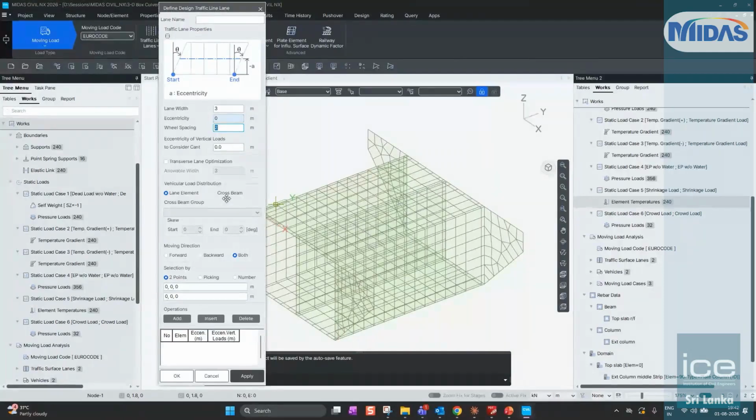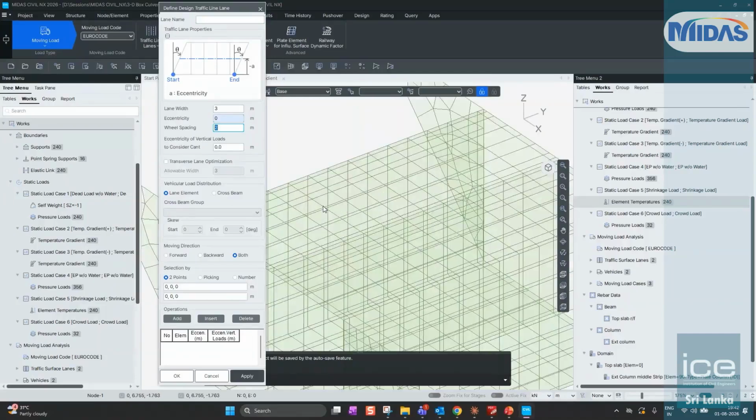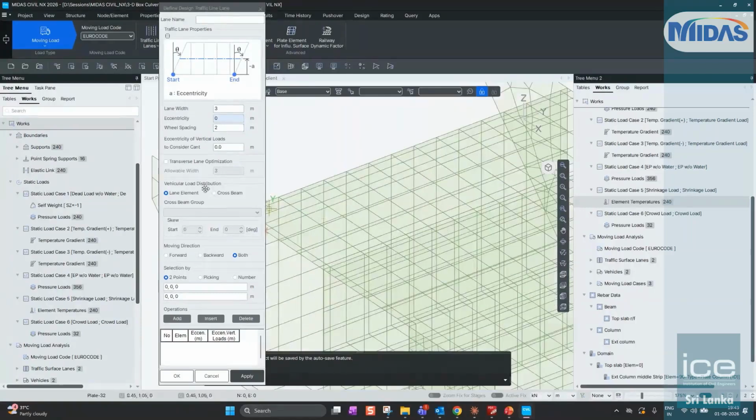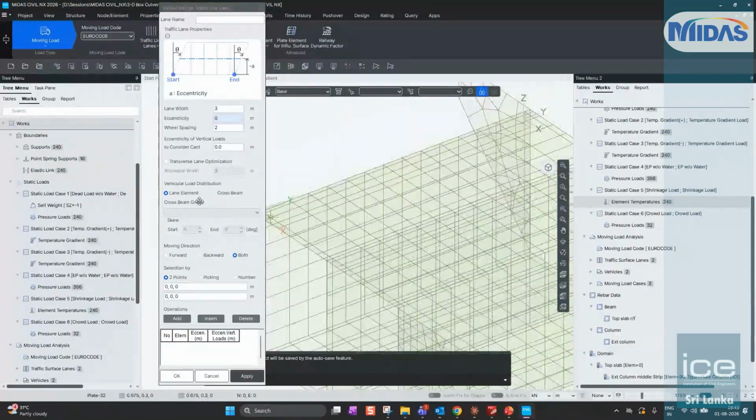When you make a beam model or the bridge model using line elements, there is no plate. So for the transverse load, what we do is we make either cross beams or we use lane elements designed for the vehicle loads, right? It is possible that the wheel load might not always fall on the single straight line where the beam is modeled. So the software allows the distribution via the cross beams. In transverse directions, instead of plates, you would model cross beams, and using those cross beams you can dump the loads on the primary girders of the bridge. Okay. Not relevant to our case though.